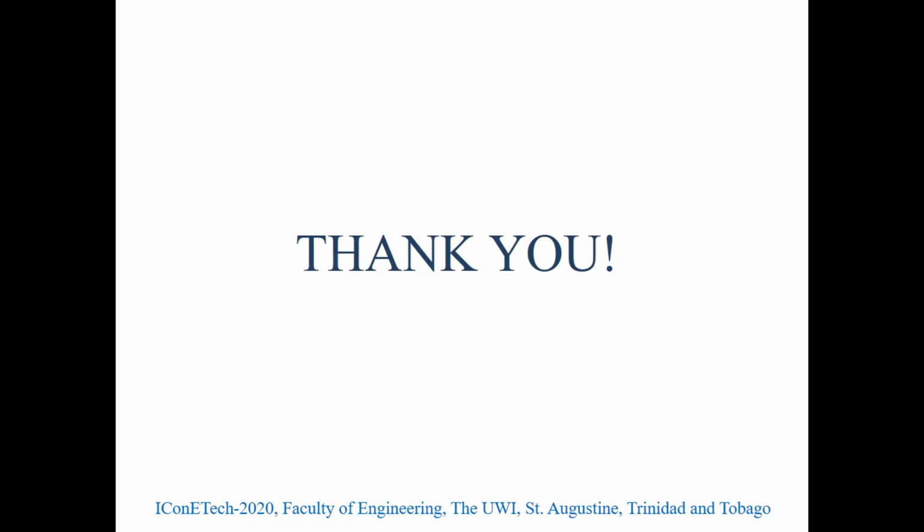In the 4 empirical models considered, was there any major assumption that could not be met in your experimental work or site conditions? Yes. So one of the possibilities for the difference in the results could be the methods they use to observe the wave runoff. So I use traditional surveying, and some would have used video monitoring techniques. Also, with respect to the wave conditions, I would have modeled my wave conditions from an offshore buoy, where they would have directly measured their offshore wave conditions. So those things may come into play with respect to the difference in results.